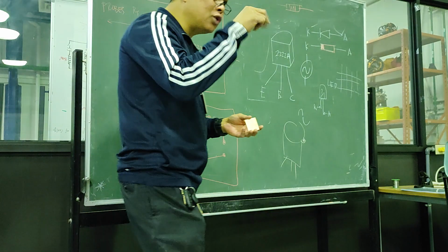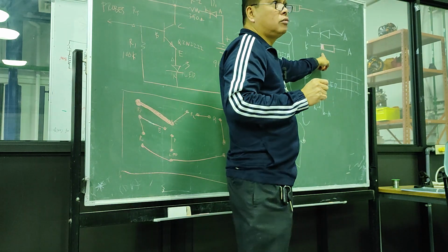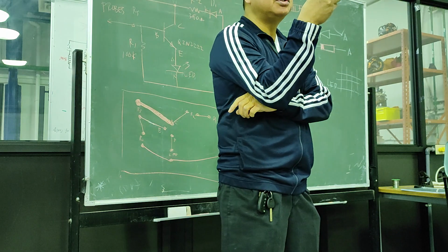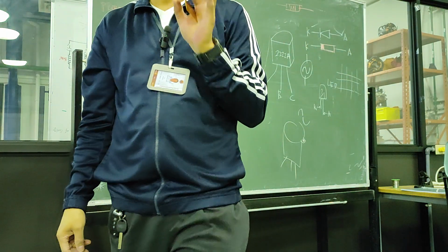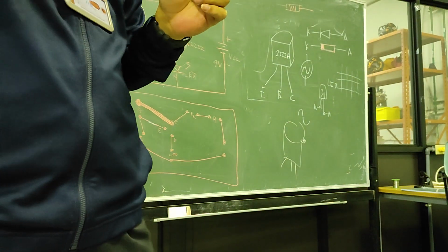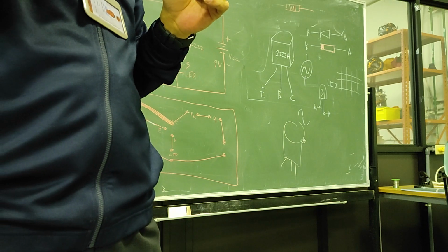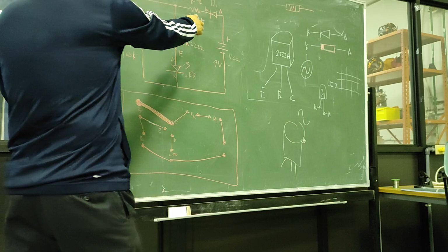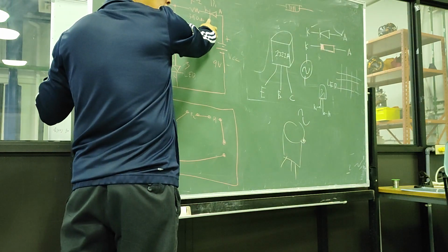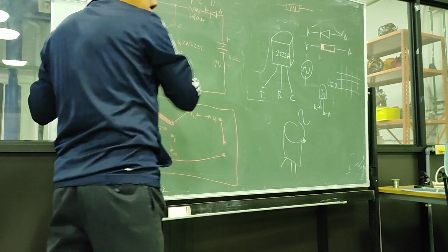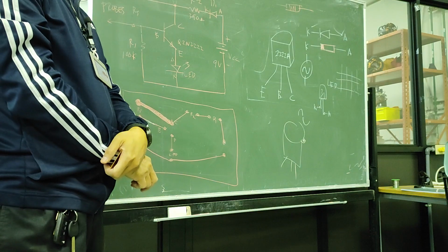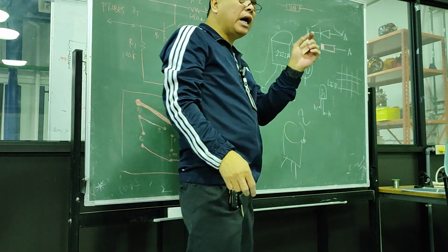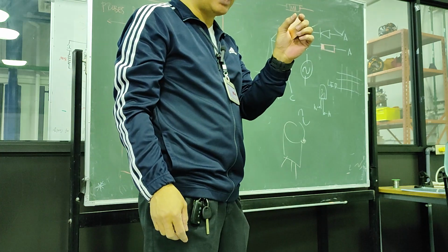Next, the diode. You must know the diode also, because a diode has two terminals, the anode and the cathode. So you cannot reverse it. There's a polarity, and it's important, so you must know where to put the cathode and where to put the anode side. Same thing with the LED. An LED has a cathode and an anode side.